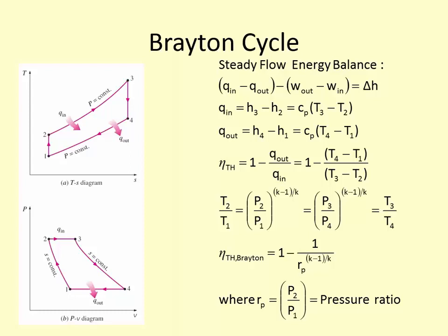And if, again, we're making the air standard assumption that these exhaust gases are actually just air, then we can say, okay, for the ideal Brayton cycle, this is an isentropic process from state 1 to 2 and state 3 to 4. So if I'm assuming ideal gas, constant specific heat, and isentropic, then I can use these assumptions which hold true there.